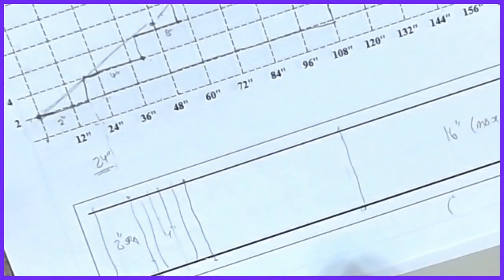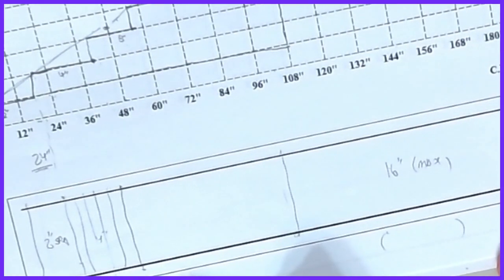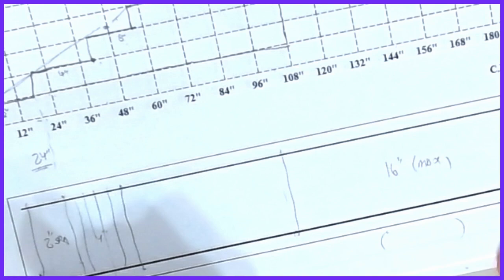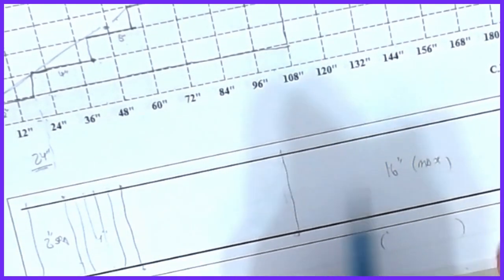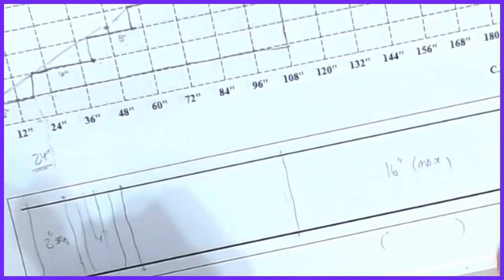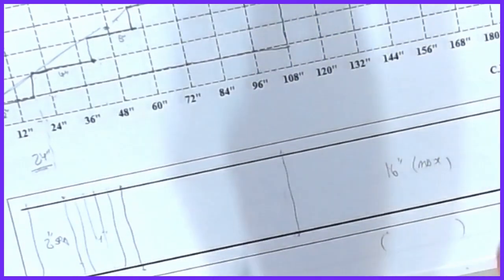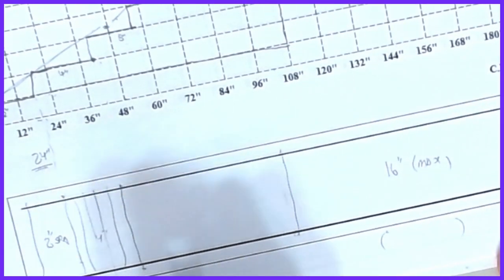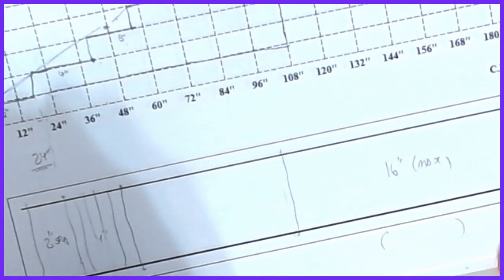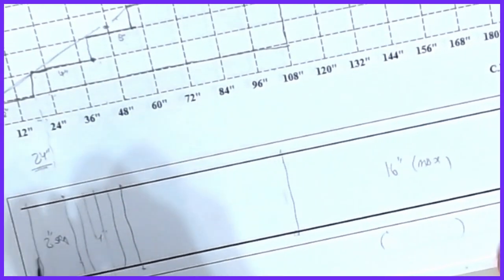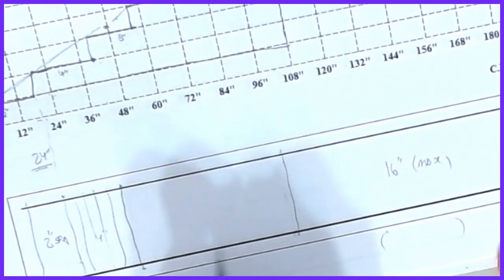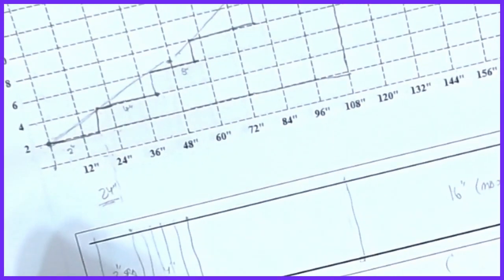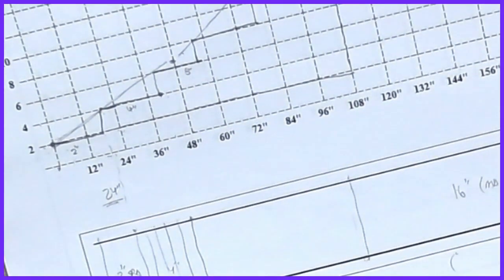And so this is something that some of the steel detailers will start to do when they're reinforcing, because in design, every one of these stirrups is designed the same way. Generally, you don't mix and match. I don't have number 4s here and then number 3s. We don't like to do that very often. Maybe in a strange circumstance we do, but we make them all the same. We just vary the spacing so I can use the same bar. And now the people in the shop can mass produce these stirrups to meet your needs, and then you as the engineer control that by adjusting the spacings accordingly. But that's the approach to dealing with these stirrup spacing curves.